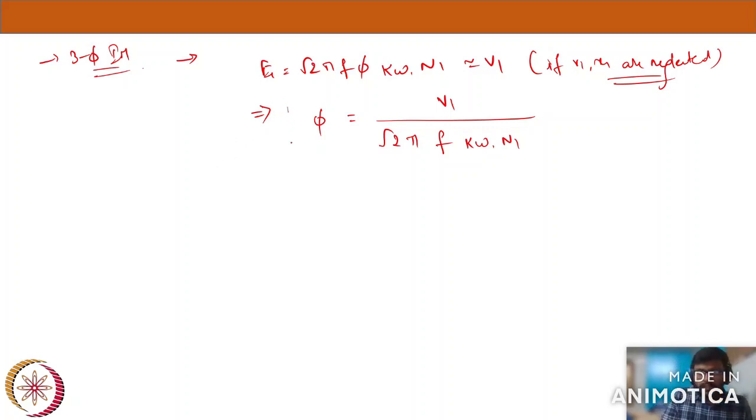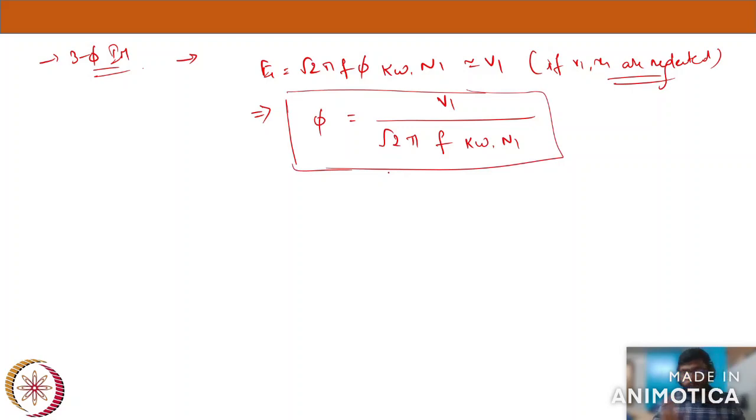Now just now we discussed the concept. I know what amount of flux per pole is required to magnetize my core. Now I know the value here that you are seeing directly. Whatever I do to my secondary, whatever I do to the rotor terminals of my induction motor, it should always give the same amount of flux that you are seeing here. That's the concept we just discussed.